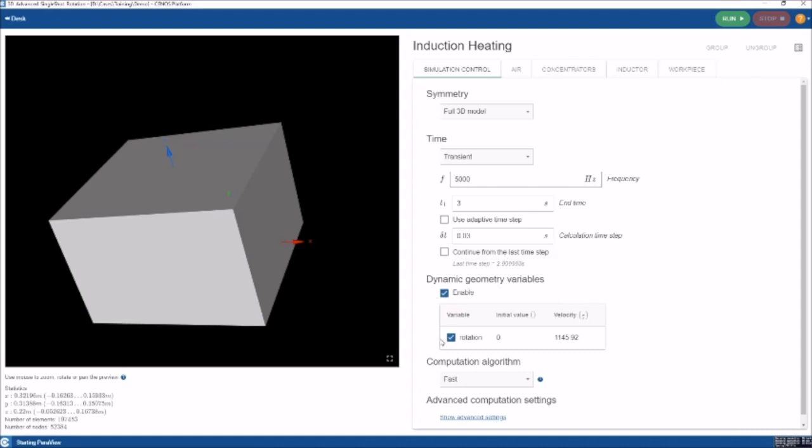And the last thing here is rotation. You can see we defined rotation, and this is velocity in degrees per second. You can also select RPM and RPS, it's not a problem. And in this case, the full rotation of the spline CV joint was simulated.